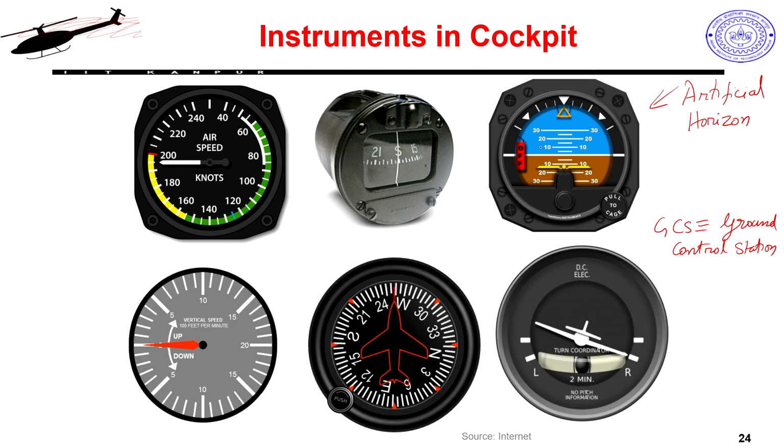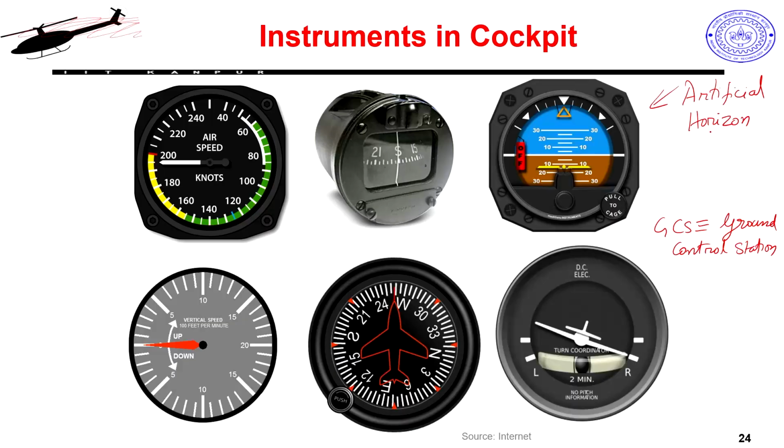Okay. So it goes to 10 degrees, 20 degrees, 30 degrees. If I see more of brown, which means I am descending, so I am looking at the ground. So this is actually visual feedback for a pilot or the operator of the UAV, and he can immediately take some action if he is manually controlling it, or if he sees some anomaly, he can try to interfere and balance things out. So, this is one, the artificial horizon.